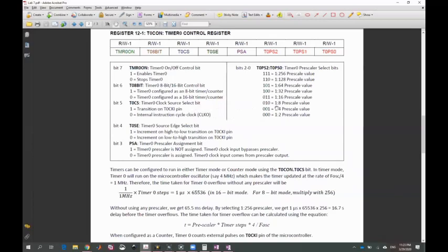In this case, you have to measure the RPM with respect to time. RPM stands for rotations per minute. So you'll need two timers here. One timer can be configured as a counter which counts transitions on the external pin, and another timer to keep track of time. After every 1 minute, you have to see how many pulses you have in 1 minute, and you can indicate that as the RPM of the motor.